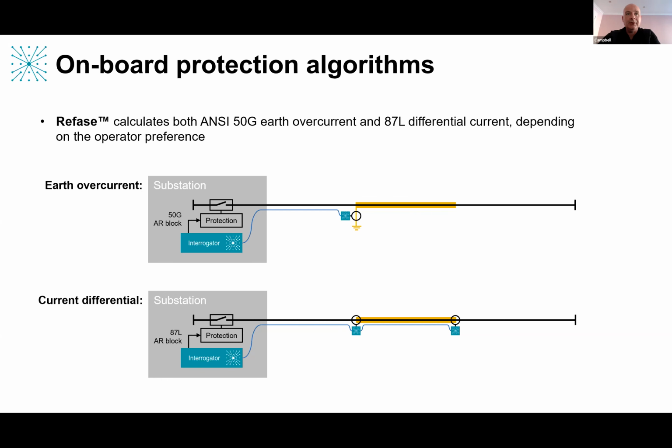Yeah, absolutely. I think that's a pretty comprehensive answer. The other thing is if you're monitoring the phase currents, then you get a few bonus features from that as well. Like we can look at the power quality in those phase currents, and also generate synchrophasors if that's required. So protection, as Campbell says, is the main distinction.